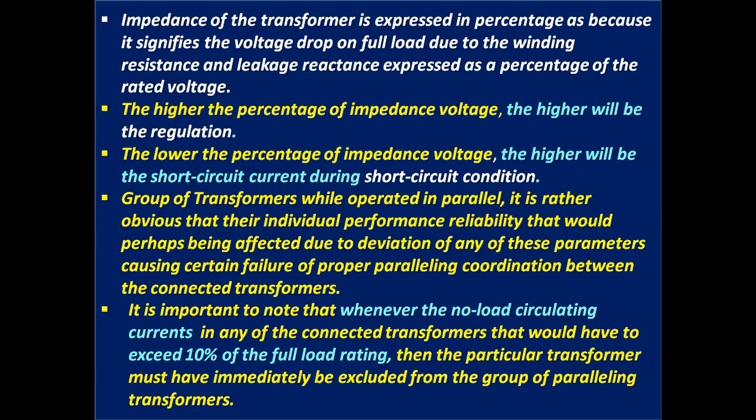It is important to note that whenever the no-load circulating current in any of the connected transformers exceeds 10% of the full load rating, then that particular transformer must immediately be excluded from the group of paralleling transformers.